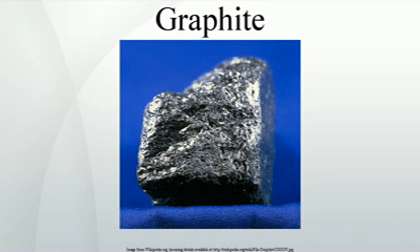For this reason, the U.S. Air Force banned its use as a lubricant in aluminium aircraft, and discouraged its use in aluminium-containing automatic weapons. Even graphite pencil marks on aluminium parts may facilitate corrosion. Another high-temperature lubricant, hexagonal boron nitride, has the same molecular structure as graphite. It is sometimes called white graphite, due to its similar properties.